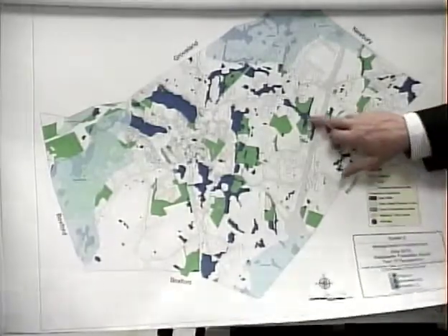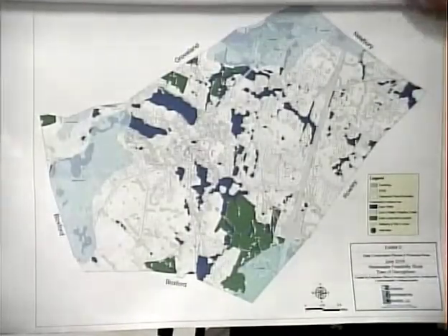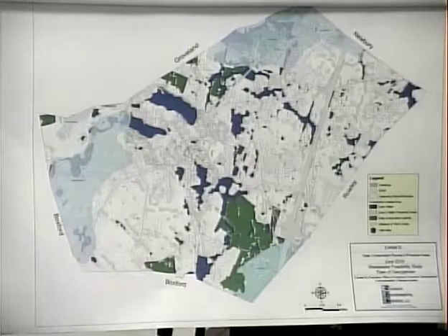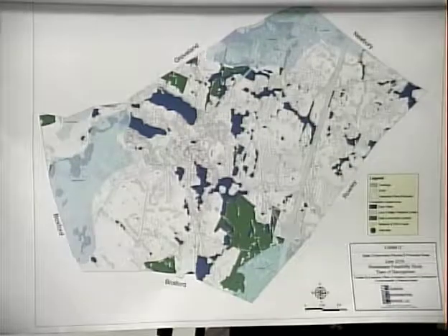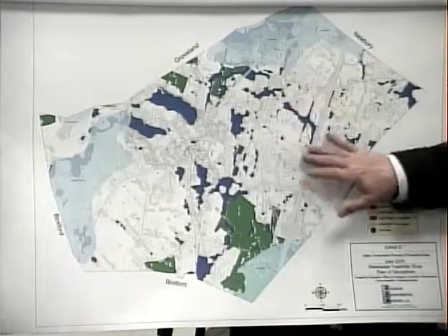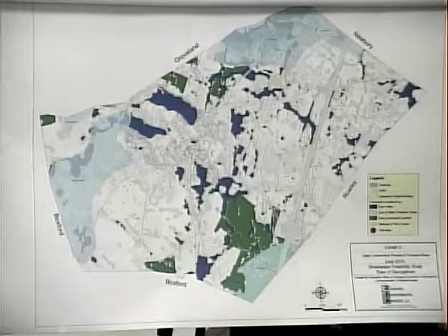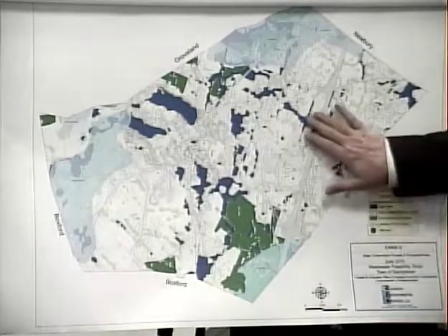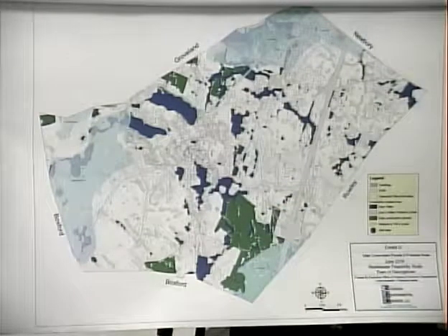We also have the wetlands, which are dispersed on a lot of the parcels. And again, one thing, when you're siting a system next to a wetland and you generate this mound, that groundwater mound or elevated groundwater table can't be allowed to break out before it hits a water supply or a wetland. So for our proximity to some of these water supply areas or water resource areas, we would need to provide proper offset and probably some filling to make sure that we don't have breakout in those areas. So these tend to be a little bit more restrictive. Wherever you see a water body in there, we usually have to have a larger offset.